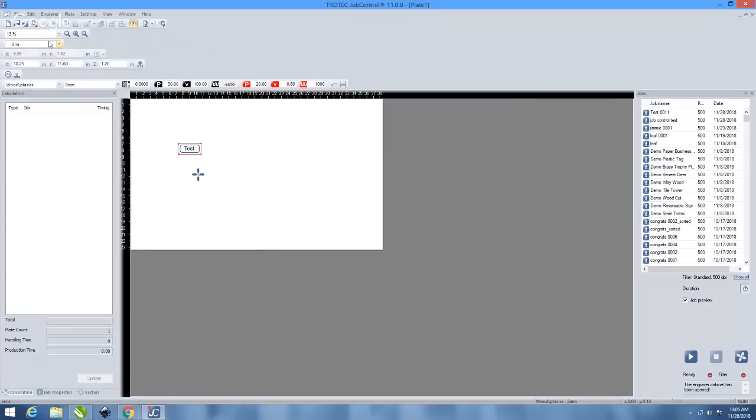So moving on here, not only that, it'll give you an error if you have the wrong lens. If you switch lens, it'll give you an error. Like if you don't want to shoot a fiber laser source into a CO2, it'll pop the lens. So it'll give you an error before it does that. Yeah, anytime you're switching to a fiber lens, you should get prompted before doing so.